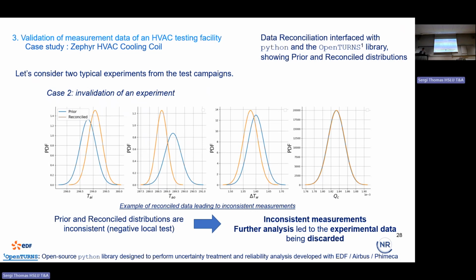Just a point regarding the conclusion of data reconciliation. Data reconciliation does not tell you which sensor is faulty in the process. It tells you something is off, and you should investigate the reason. For instance, here, maybe we could think it's this sensor, but in the end, it's not. So it tells you something is wrong, but you should have a better analysis on the reason.